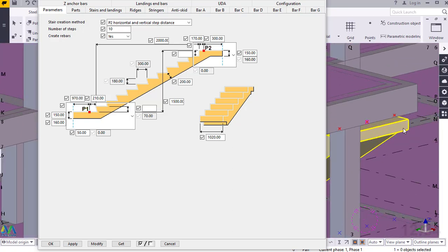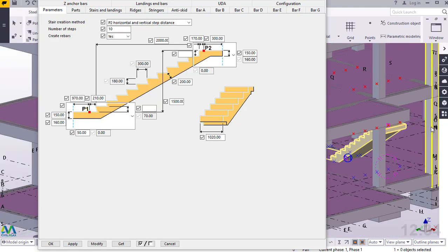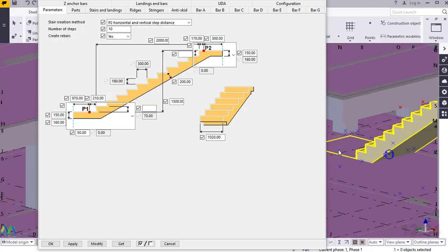Now this is our landing, and we want to extend this to be closer to these two columns. And also we want to get rid of this bottom landing, because we are starting our staircase right inside this bottom slab. Now to do that, we'll get rid of this dimension here. We'll make this 150 instead of 970. Then this one, we'll adjust these to 1.53, 1.35. I'll feed that. Then we'll come here and add